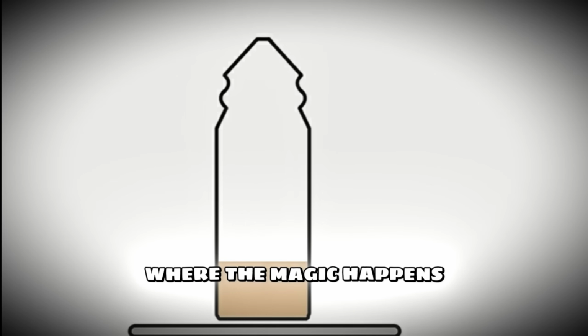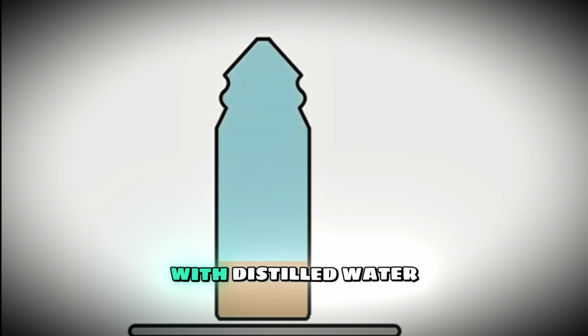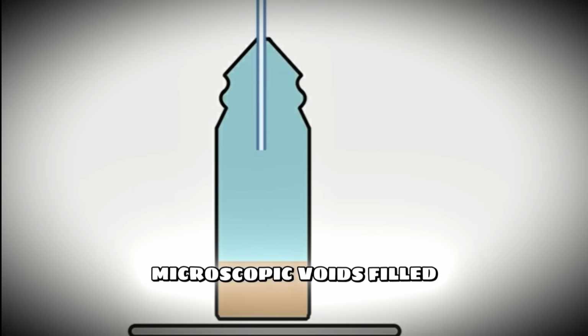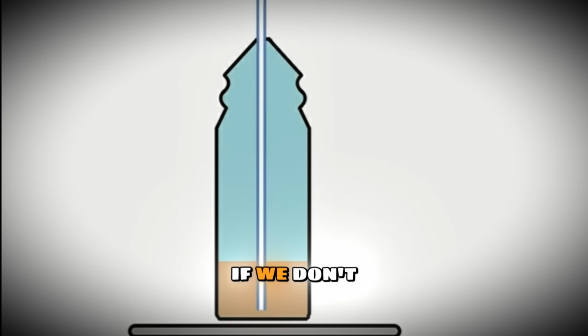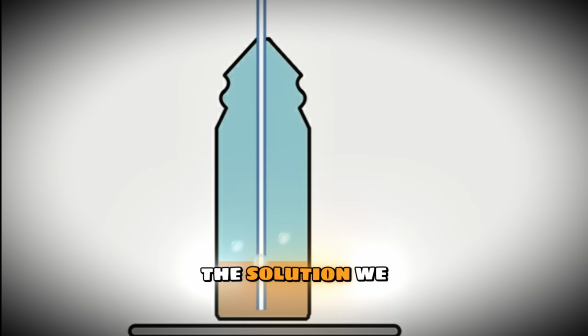Step 3 is where the magic happens. You fill the jar about 3/4 of the way full with distilled water, but here's the problem. Soil has tiny microscopic voids filled with air. If we don't get that air out, our volume calculations will be ruined. The solution? We agitate it. You can apply a gentle vacuum or carefully boil the jar, rolling it to release all those trapped air bubbles.